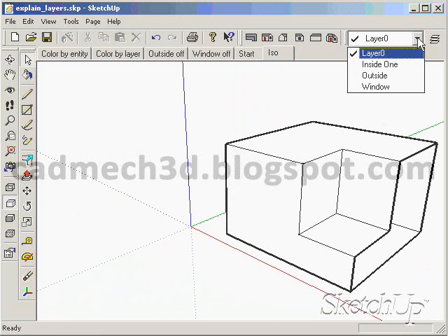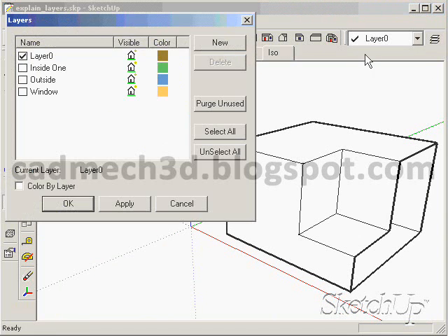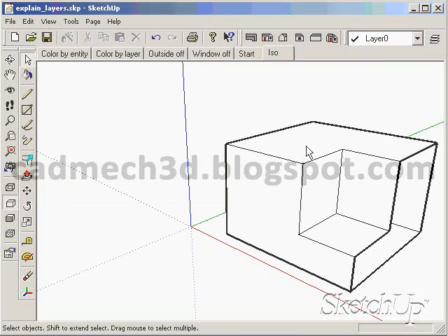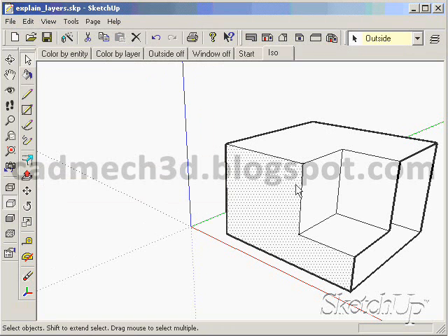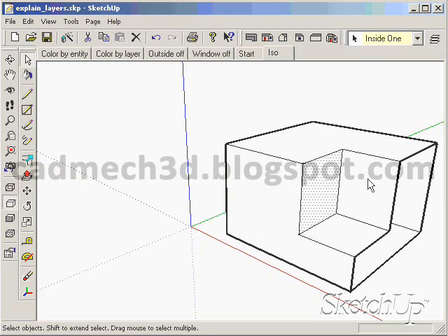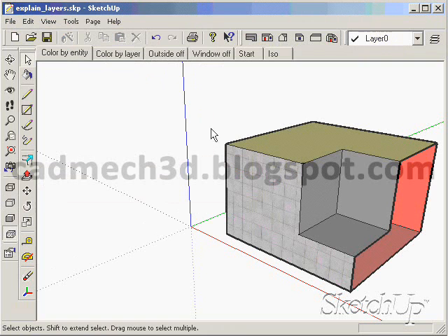Layers in SketchUp are also unique. They are used to control visibility only. They do not isolate geometry, since all faces share edges across layers. Notice the layer drop-down list shows the current drawing layer name shown with a check. As you select a surface or edge, the layer for that object is listed with a select arrow. Clicking away from geometry clears the selection.